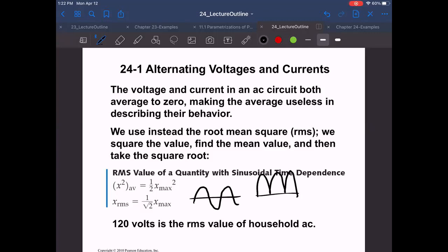You are then going to take the mean of it, the average. Actually, technically, I should make it really close, because it turns out for sines it's 1/2. And then, because we don't want the average of the squared value, we take the square root of it. And that brings it down like that. So it ends up giving a better idea of what the average is in there. The root of the mean of the square. Square it, take the average, take the square root. Have you all ever done that in any of your math classes? All right, so that's your root mean square.